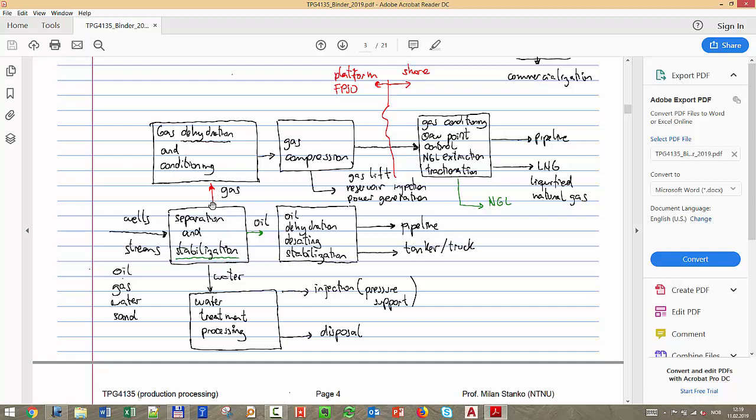But when we take the gas further, for export, we want to compress it, we want to inject it, we want to sell it, that gas still has quite a lot of water content. That means that any change we make in pressure and temperature might cause water to come out of solution, water simply to condense from that gas. And that can cause a lot of issues downstream. We're going to see only a few of these issues, but it can cause corrosion, can cause hydrate, can cause scaling, can cause many, many things.